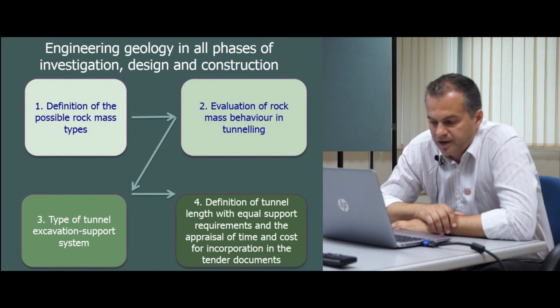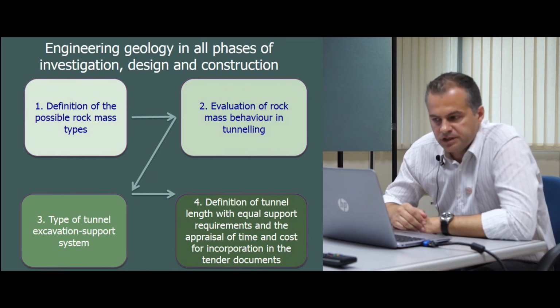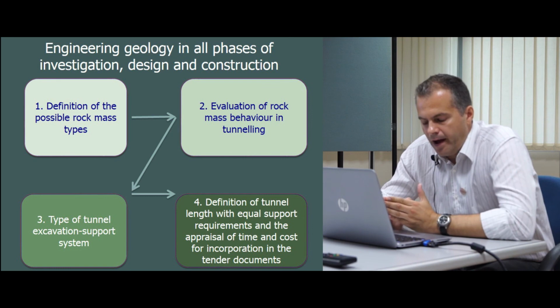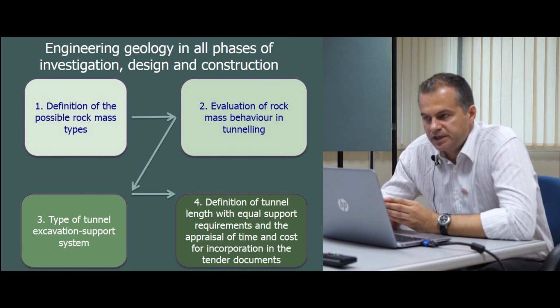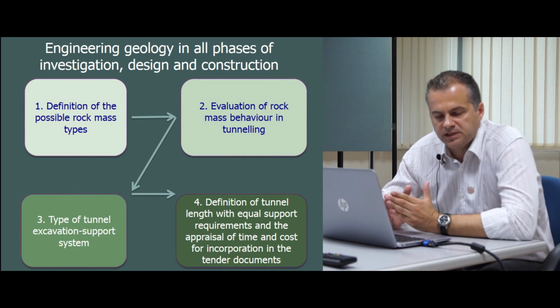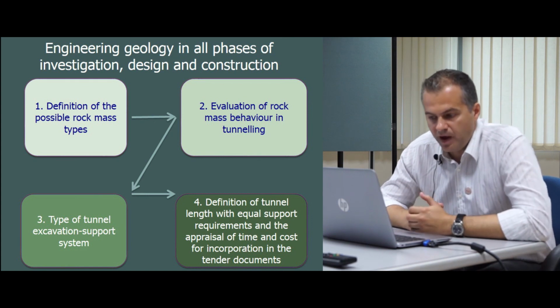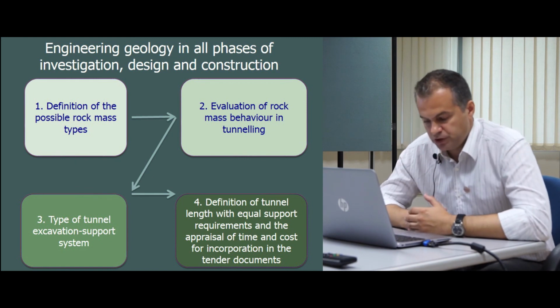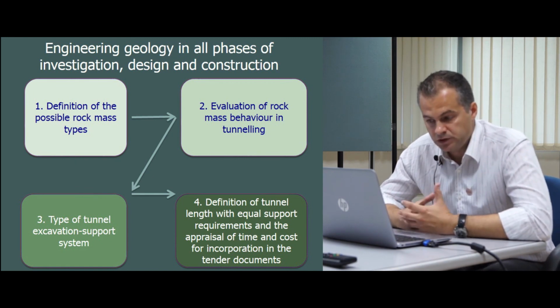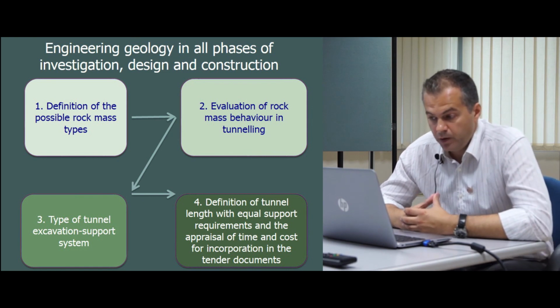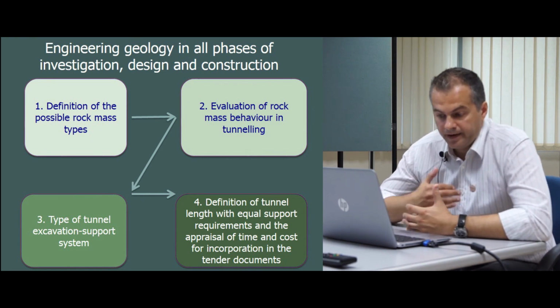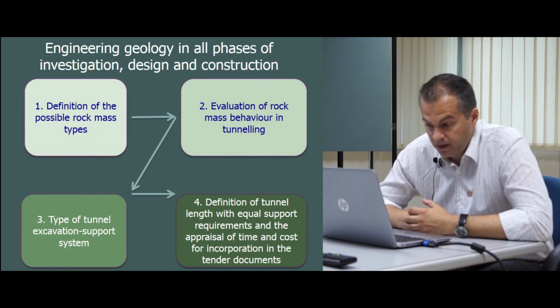So ending this webinar, in this methodology, engineering geology is in all phases of investigation, design, and construction. Here, our responsibility does not lie just in defining a rock mass classification system for the tunnel design. We need first to identify the rock mass types, the ground types, either by using any rock mass classification system or our own rock mass classification system for the case we need, and then to evaluate the rock mass behavior in tunneling, and provide the tunnel excavation support system dictated by these behavior types.